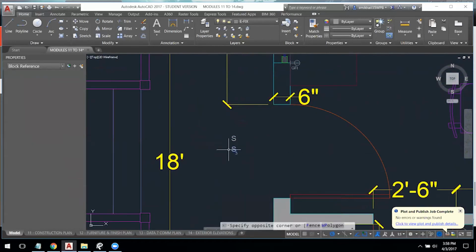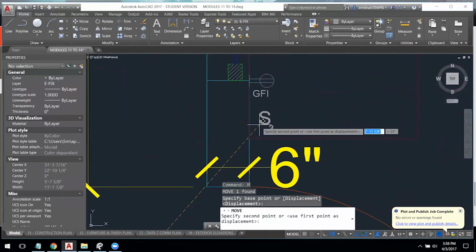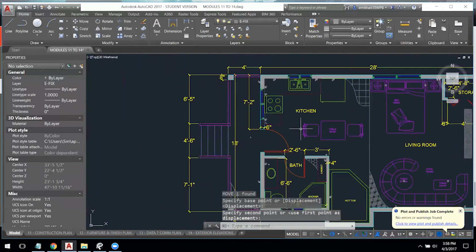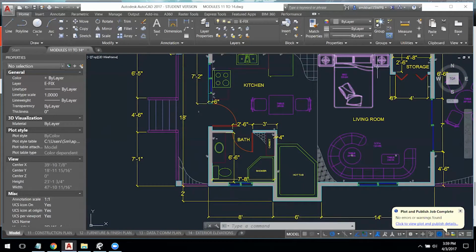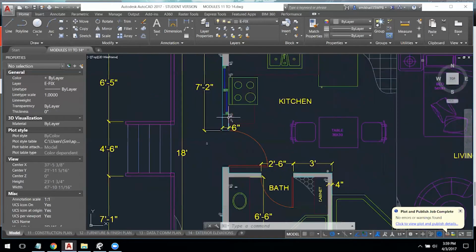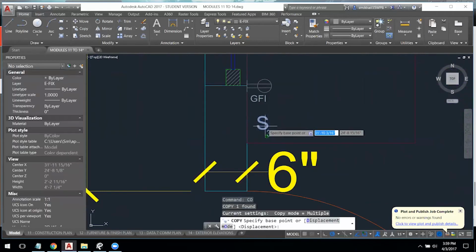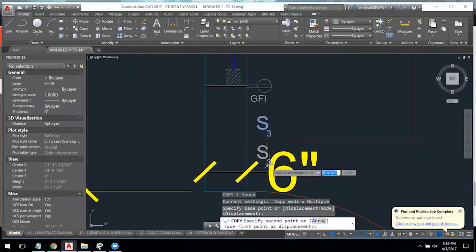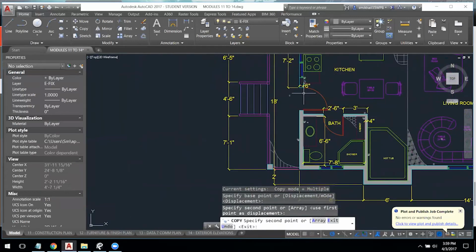So I'll take this guy, move it, and put a three-way switch in here. What am I turning on? Can I possibly be able to turn on these lights in here? I should. So if I have guests over, with one flick, I can turn on all the lights in my open area. So that means I will need two three-way switches in here. Okay, so that takes care of that.